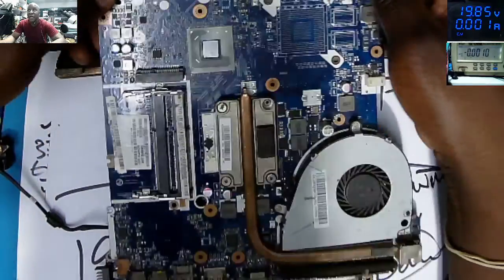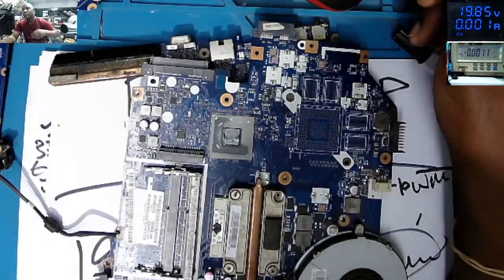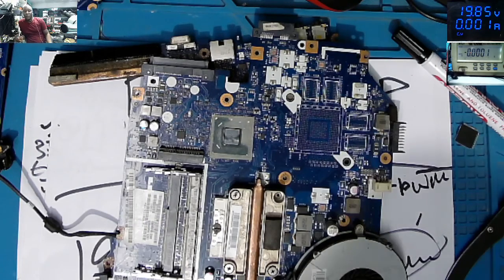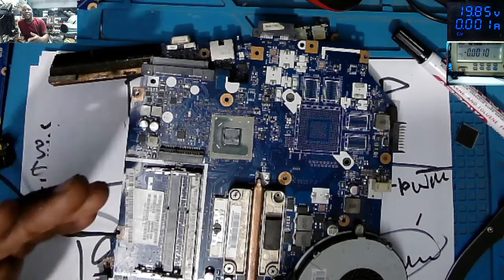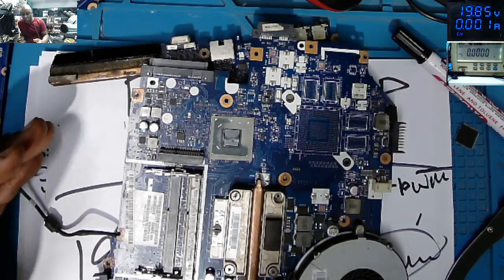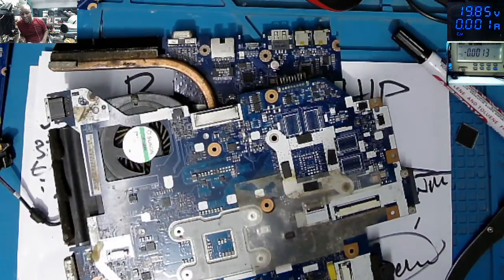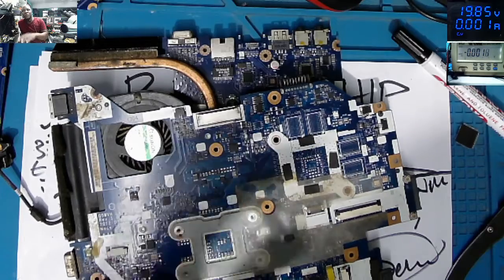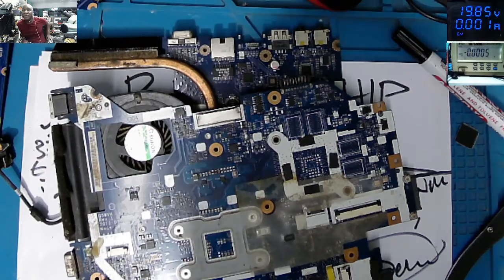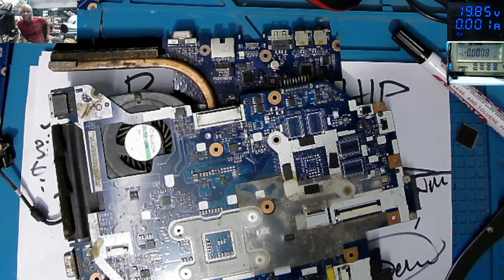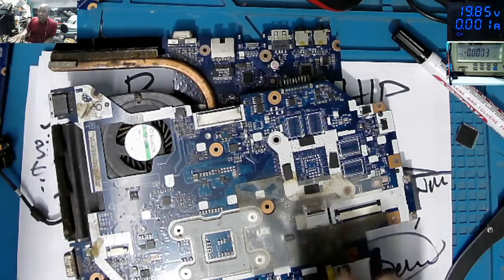So the motherboards, nothing is hard on fixing motherboards. Focus on what you know. Obviously, from the charging port, you are checking the charger first. If the charger is good, check if the 19 volts is passing those 2 MOSFETs. If there's any problem on the motherboard, in most cases, the 19 volts is not passing those 2 MOSFETs. Those 2 MOSFETs are like gates. Those are the main gates for the motherboards. Because in order for 19 volts to pass these 2 MOSFETs, everything must be right.